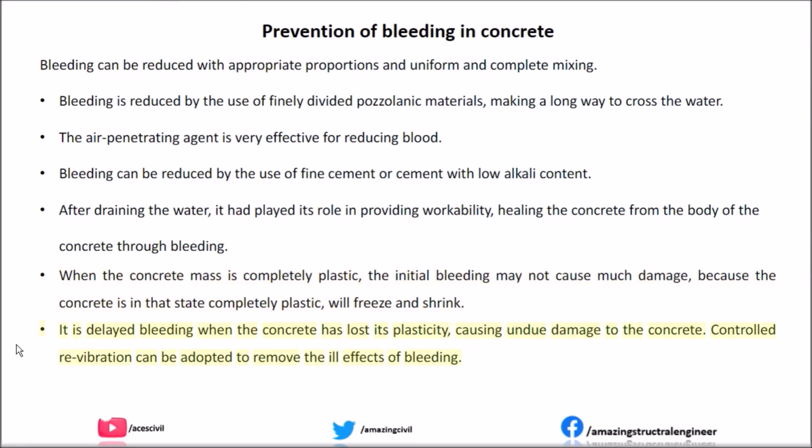It is delayed bleeding, when the concrete has lost its plasticity, that causes undue damage to the concrete. Controlled revibration can be adopted to remove the ill effects of bleeding.